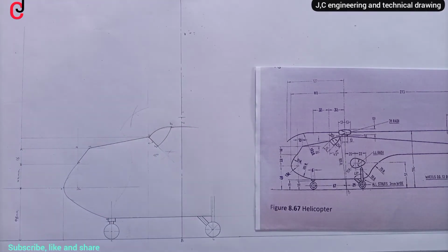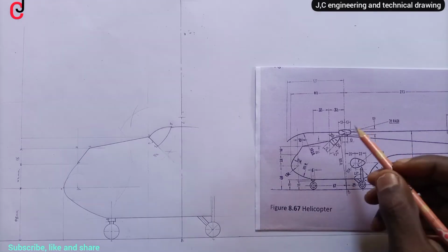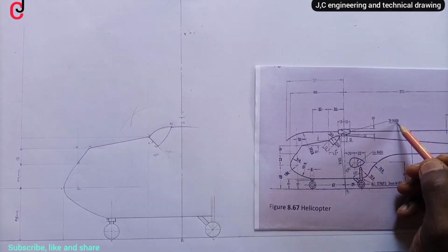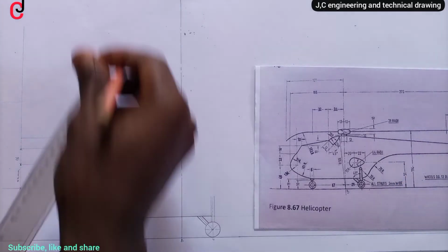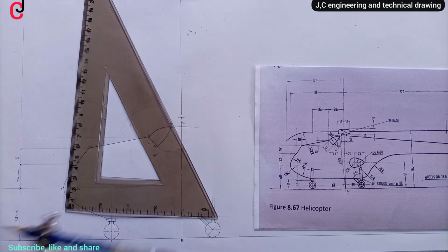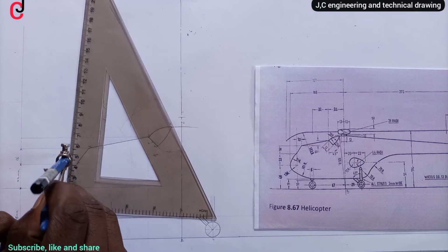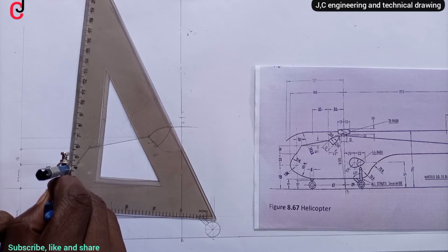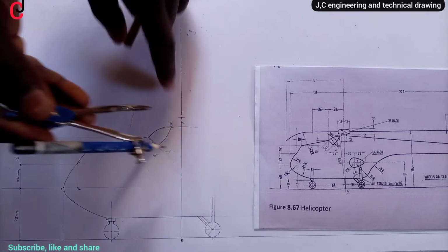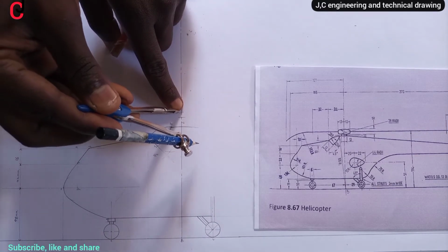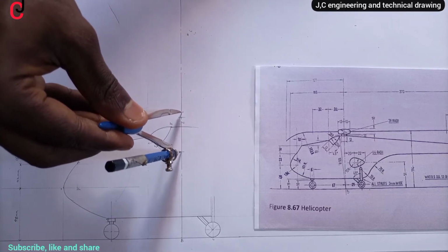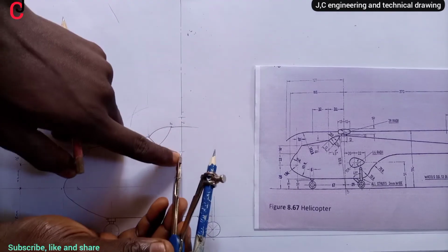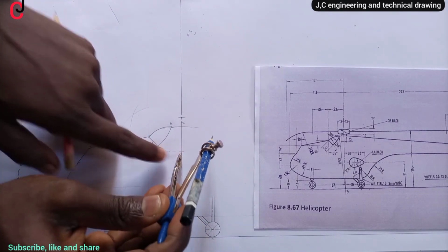Now using point 1, see the curve over here is given to us as radius 38 millimeter. So pick 38 millimeter radius from our rule. Now place it at point 1. Now describe an arc downward using the points that bisect the vertical line.